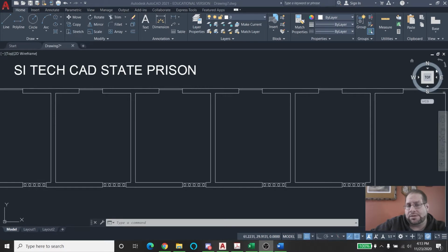AutoCAD. Now, the block command is something that's used often to group items in CAD, but it's really for something more than that. Usually, when you want to use an item multiple times across multiple drawings, you use the block command to create that item, and then you can manipulate it afterwards and use it as many times as you want within a drawing, or again across multiple drawings. And as you edit that item, it does get updated across all of the items inside the drawing.